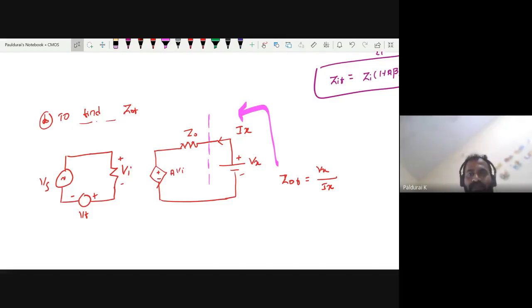என்னது? In order to find Thevenin resistance, you want to kill all the independent sources, right? So that is the very first point. Then open the load, then okay. So you want to make actually Vs equal to 0. You want to kill means you want to replace voltage source by short circuit, current source by open circuit.